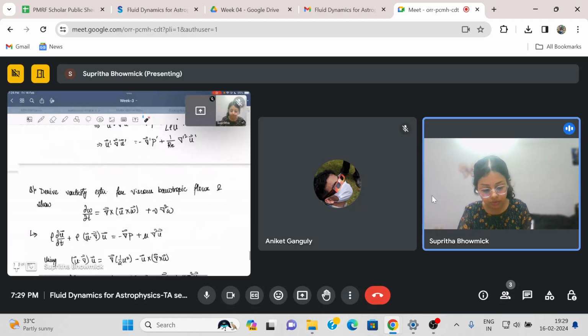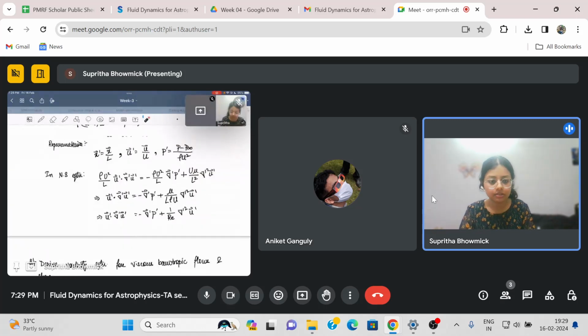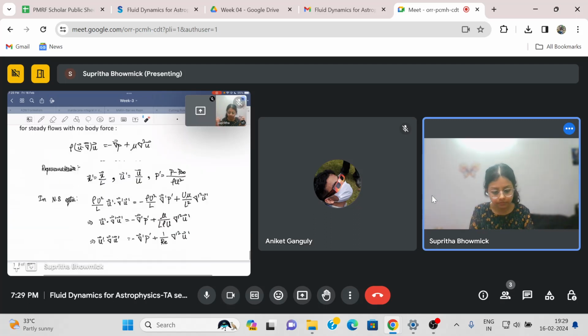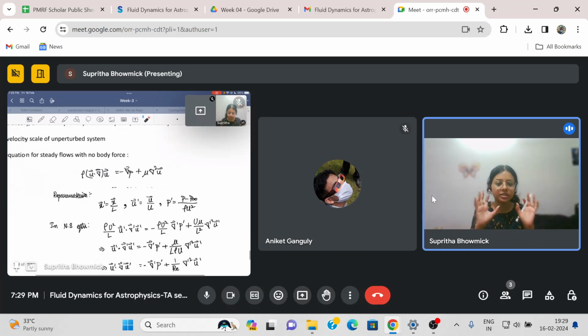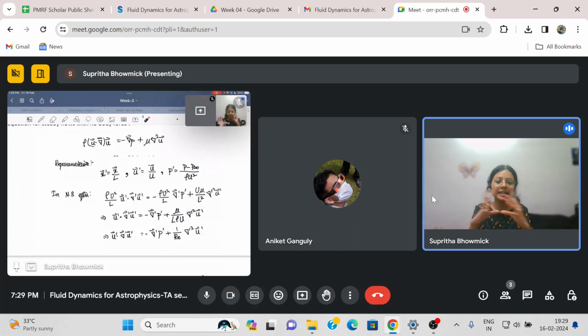And this is a nice equation to work with because as long as you are working with two systems which differ in sizes, by two systems I mean two fluid systems with some solid objects submerged in them, and these solid objects have the same geometric shape, if these systems are scaled versions of each other, this equation tells you that the flow profile for both of the systems will be the same.